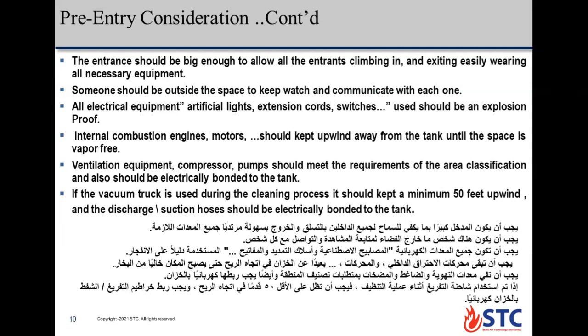Also, someone should be outside the space to keep watch and communicate with everyone inside. This is very important for any work in a confined space.